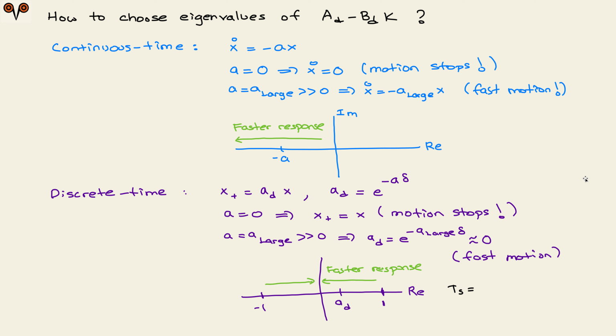To use the pole placement command, the place command, you need to understand that you shouldn't randomly choose desired eigenvalues inside the unit circle; there is also a meaning to it, like faster response, and so on and so forth. I would like to make a resemblance to continuous time control, and how you can use your continuous time knowledge to understand how you choose eigenvalues in discrete time.